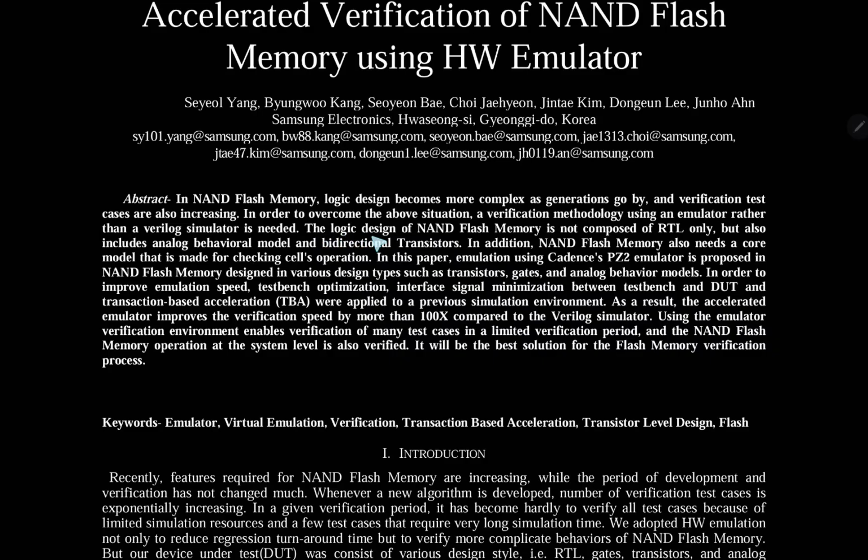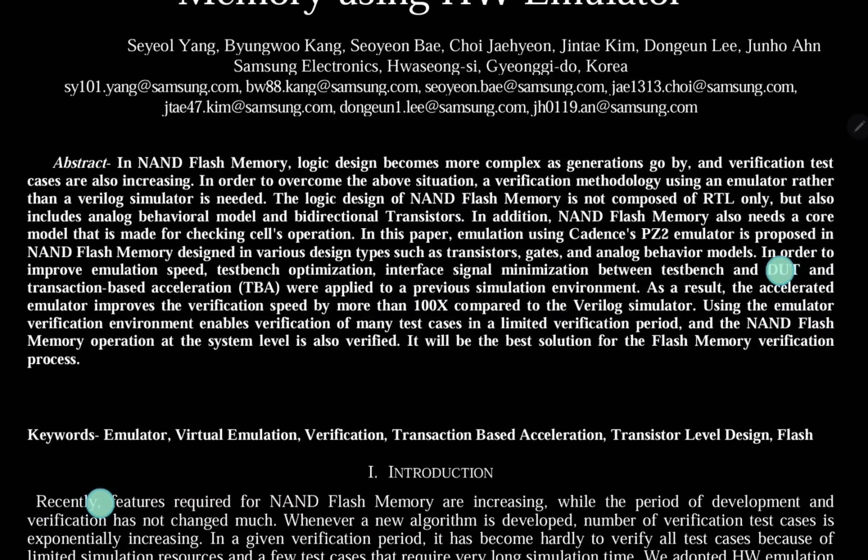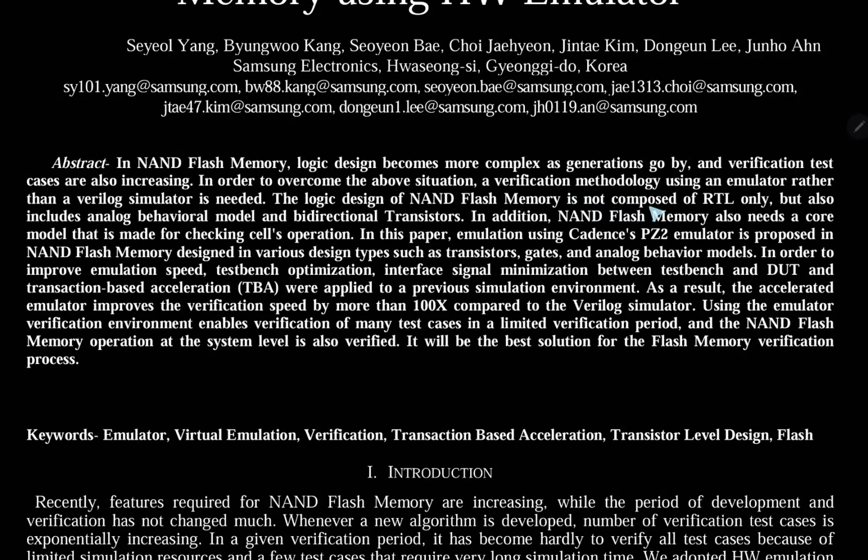So the logic design of NAND flash memory is composed of not only RTL, but also includes analog behavior models and bidirectional transistors. In addition, NAND flash memory also needs a core model that is made for checking cell operations.